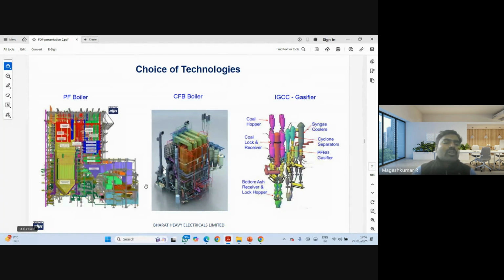Only the boiler is shown here. There are superheater coils and other things. Inside the tubes in the boiler, water flows, is heated, and is converted to steam. The steam is further heated to superheated condition in the red colored region, shown as superheater coils. Further, through pipes, it is taken to the steam turbine to produce power. That is with respect to a thermal power plant.